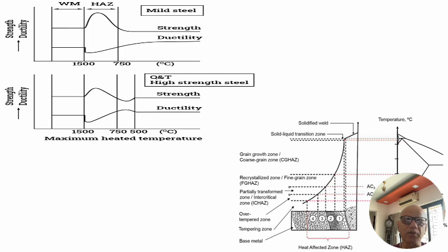Some materials have a high coefficient of expansion, so they will expand and contract to a larger extent. There are some materials which have a very low coefficient of expansion. Similarly, with thermal conductivity, a material with good thermal conductivity, like aluminum or copper, will flow the heat and make the entire surface hot. Materials like stainless steel, which have poor conductivity, will try to accumulate the heat.